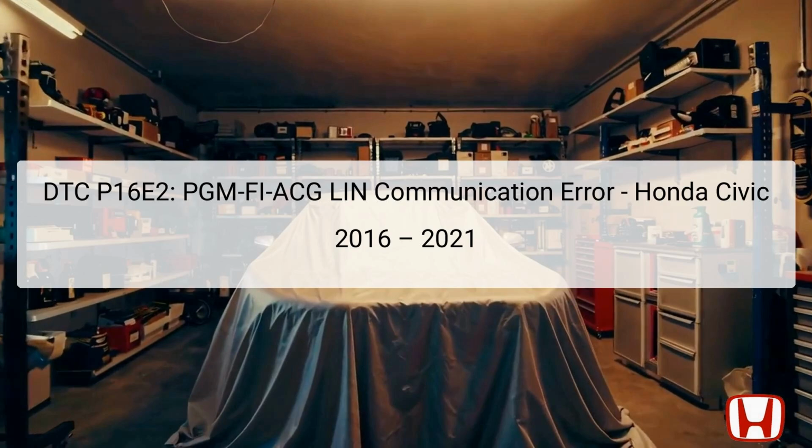The Diagnostic Trouble Code, DTC P16E2, refers to a PGM-FI-ACG LIN Communication Error, specifically indicating a communication failure within the Local Interconnect Network, LIN, bus system related to three key components: the powertrain control module, PCM, the alternator, and the battery sensor.